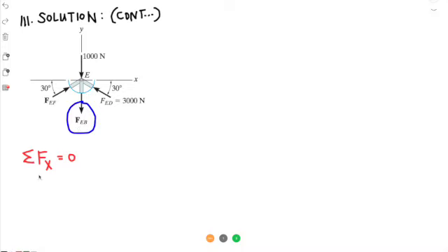So that's 0 equals, the positive one is the component of FEF, that is cosine this component right here. Let me draw it, that one. And this is the component of FED. And this component is adjacent to 30, so that's cosine. So that's FEF cosine 30, minus, this is also a cosine 30, FED this time.